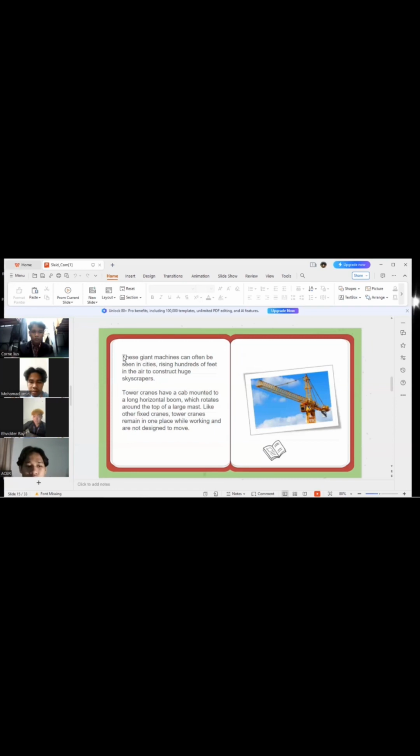So many shipyards use large gantry cranes to construct ships. A gantry crane consists of a long boom that spans between two support legs and one or more hoists that travel the length of the boom. The support legs travel along the ground, which allows a large part and module to be taken from the dock and installed on ships that are under construction.